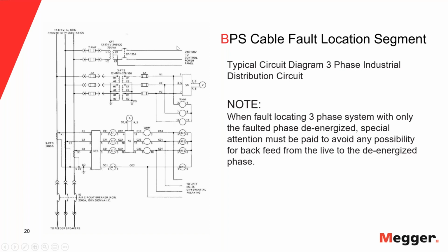On a side note, some of the old wind farms couldn't be switched around. They had all T splices in them, and it became a nightmare to fault locate. Today in wind farms, we typically have sectionalizing or switching cabinets also, to make that aspect a whole lot easier. And the most important thing, much faster.